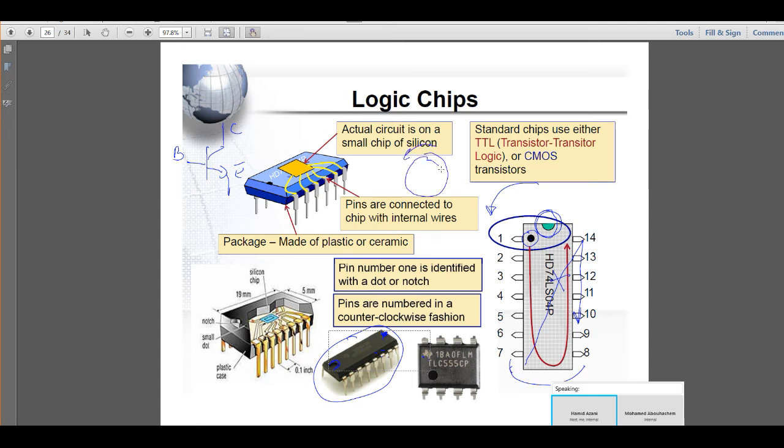Okay, the clock goes in this direction to count the minutes or seconds. For our case, we do the reverse of that. We go from that side and count 1, 2, 3, 4, 7, and continue from this side 8, 9, 10 to the last one. If we cannot see this notch, like this one, you can identify one of the corners by this hole or this circle, this black one, and from there you can count.